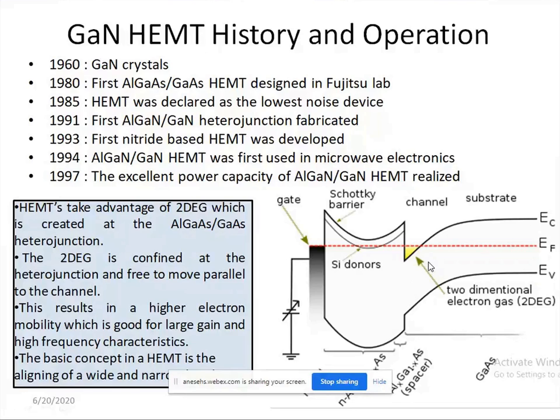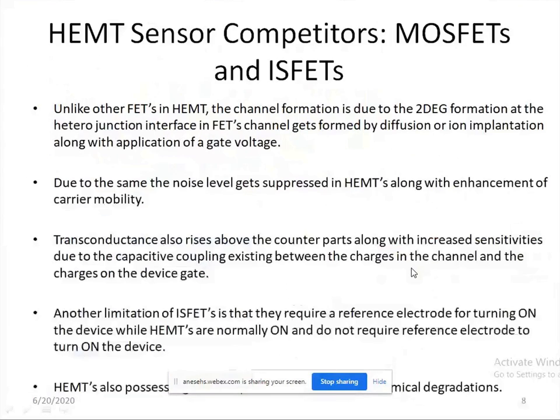So we can go to this by various methods, like by adding layers, by using gate engineering, by using different kinds of passivation. But at the end, if we check what we are optimizing, it is actually the 2DEG in the device, and it is the heart of operation of the device.